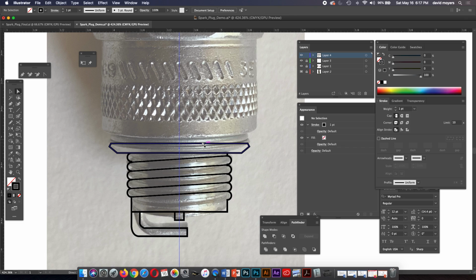All right. Now, this has a contour kind of edge. And if we wanted to show that, we would use a thinner line. So I'm just going to draw a straight line here with my line tool straight across here. And we're going to bring this down to, since it's small, maybe we'll try it at 0.5, as those other lines were 0.75.